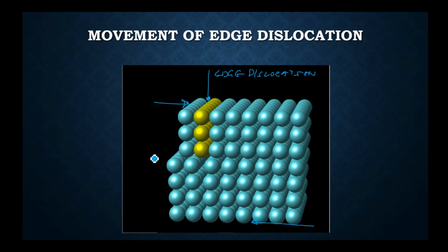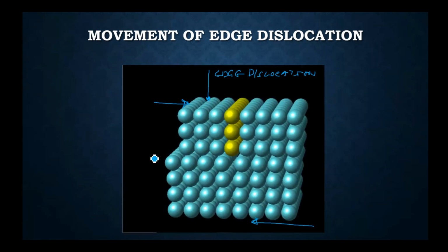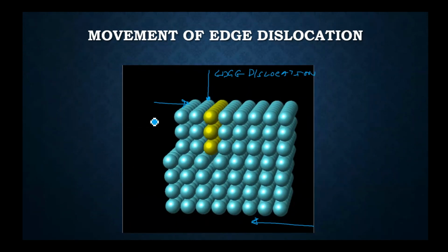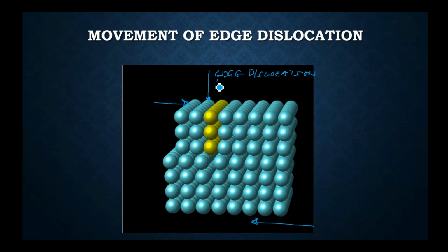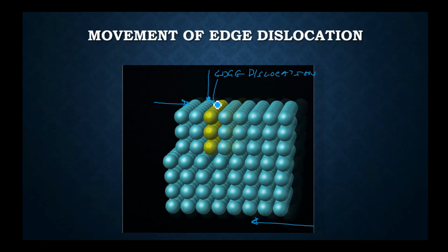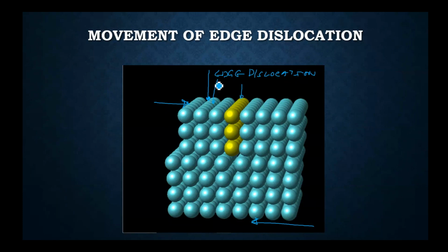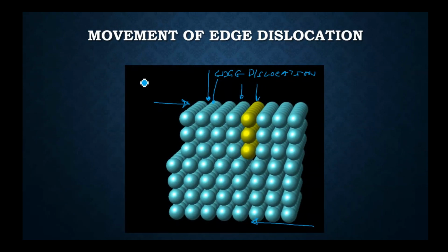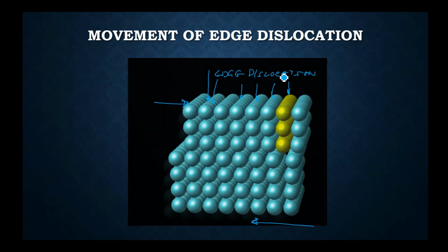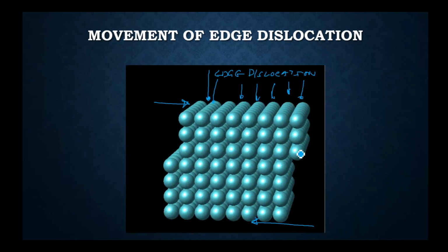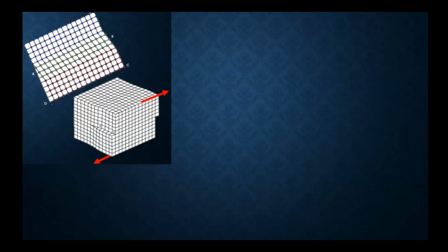in the lattice. You will see this dislocation moving in steps. So it moved from this position to the new position over here, and it moved to a new position over here, again to this point, this point, this point, and ultimately the dislocation converted into a complete unit cell step. All right. So this is how an edge dislocation moves in the lattice upon the application of shear stress.